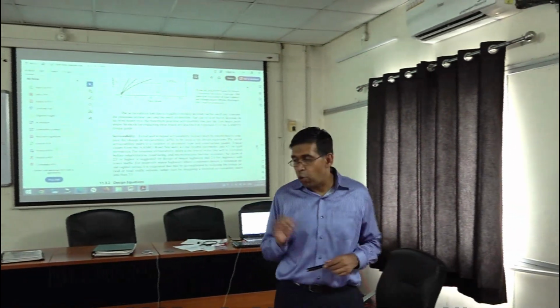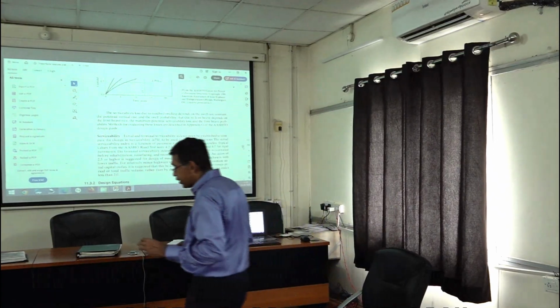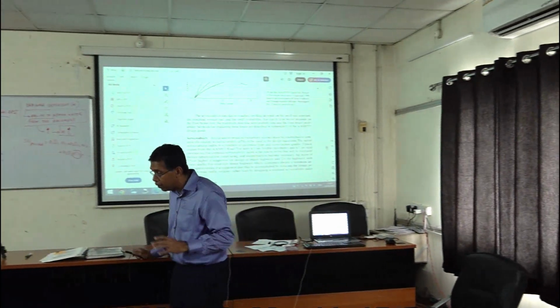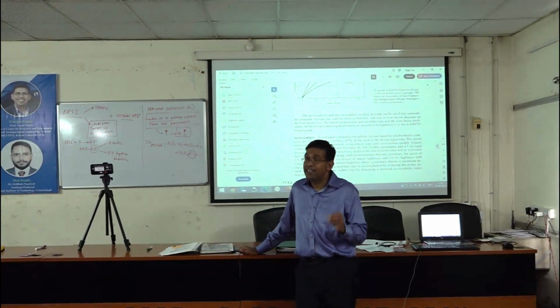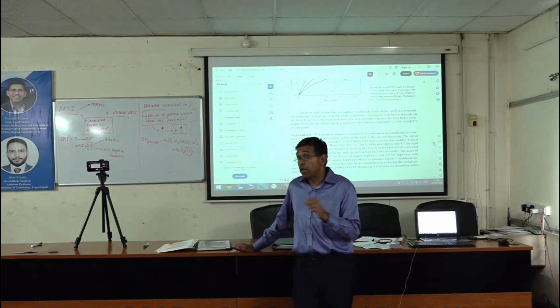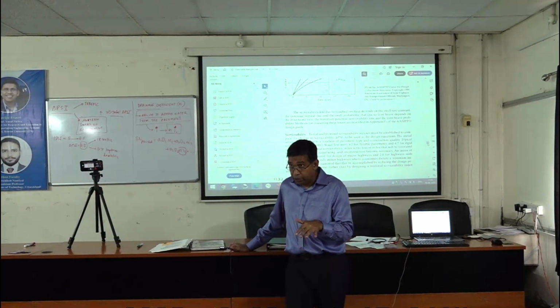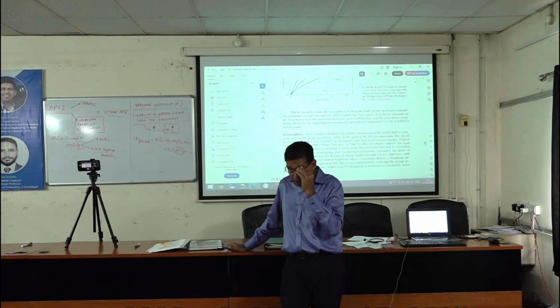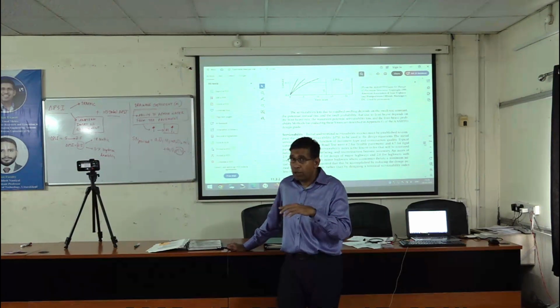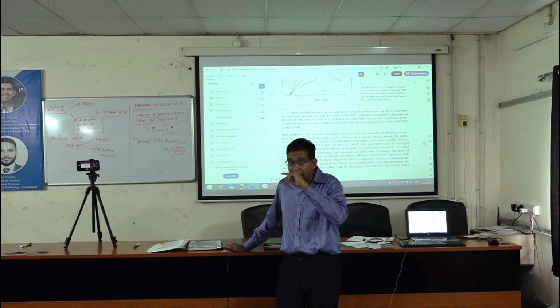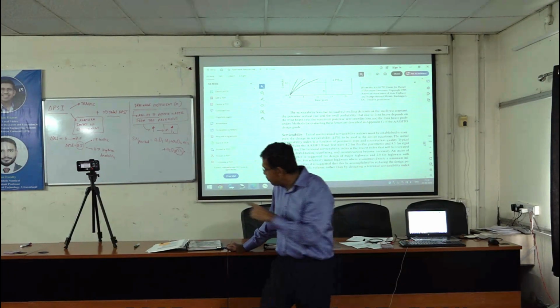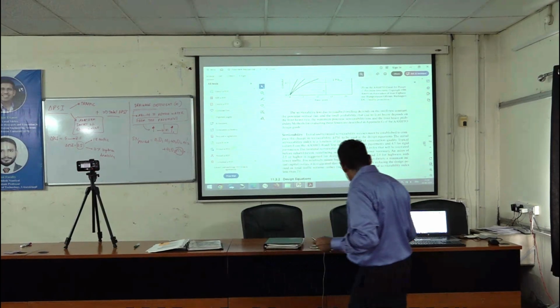The only way you will get an effective CBR of a composite layer is if you do a non-destructive test, NDT. So if you want, I can do a quick evaluation of NDT before I go into rigid pavement design, and that would be a very valuable thing to go through. You know how to do non-destructive testing? Falling weight deflectometer. Do you want me to do that? Quick recap. How does FWD work? Okay, let me cover that. That's also very important. Then I'll go to pavement design.